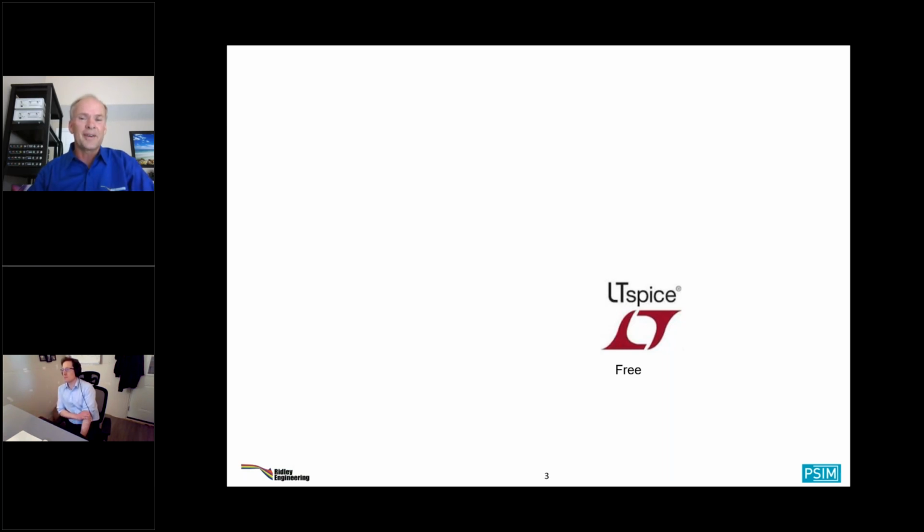And that's not just a trade answer. There's lots of free software out there, but you need free software that actually does a pretty good job. And LT-SPICE is amazing in what it can do in its small signal simulation and its transient simulation. It's really come a long way under the guidance of Mike Engelhardt in speeding up the problems of LT-SPICE and avoiding convergence errors and working really well on switching power supplies. And that always has been historically a big challenge for LT-SPICE.